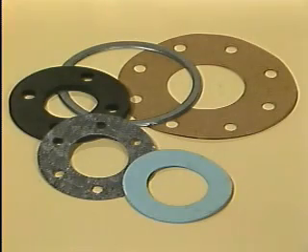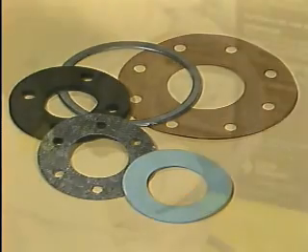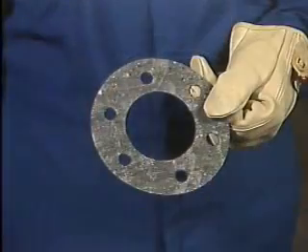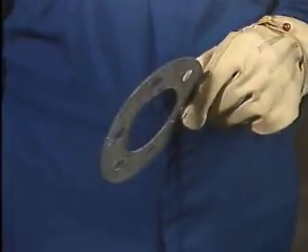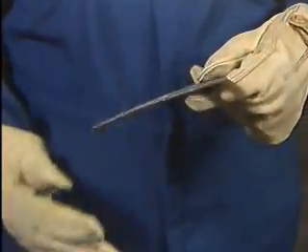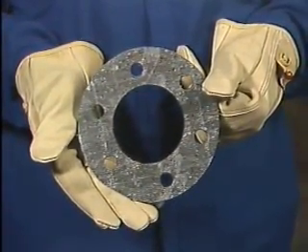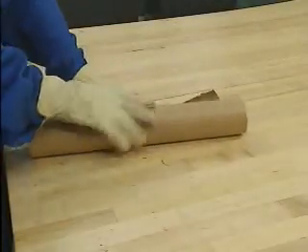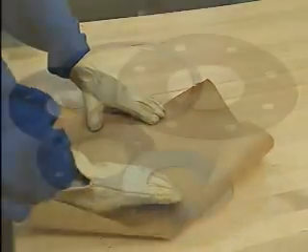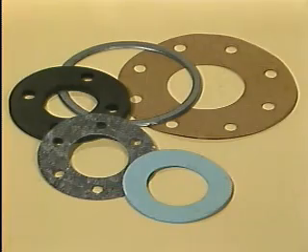There are essentially two basic types of gaskets: flat gaskets and O-rings. Flat gaskets are typically thin, wafer-like devices designed to cover all or much of a sealing surface. Flat gaskets can be pre-formed by a manufacturer, or they can be cut from a sheet of gasket material. Flat gaskets come in many varieties to suit many specific applications.